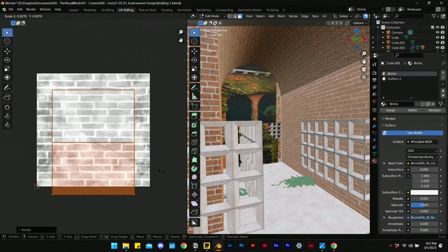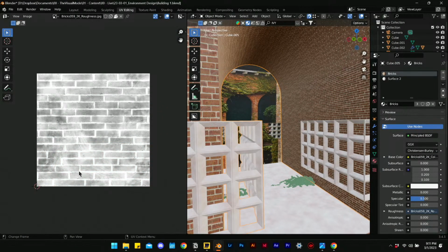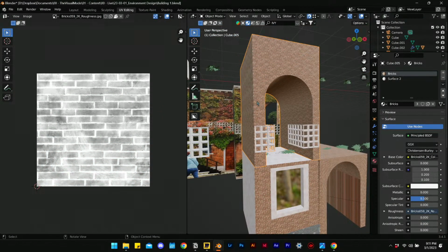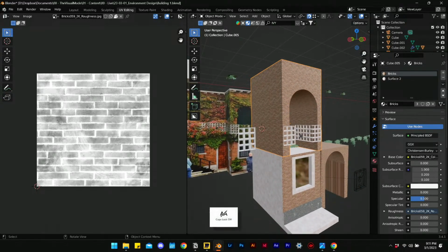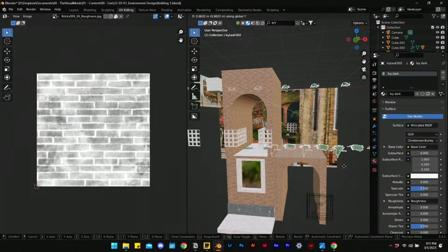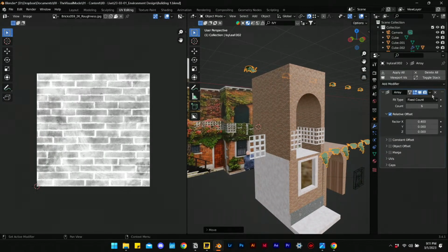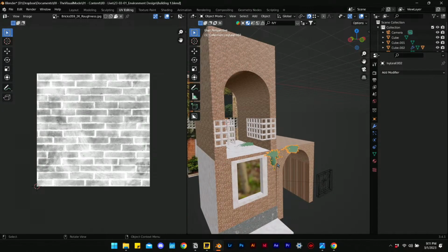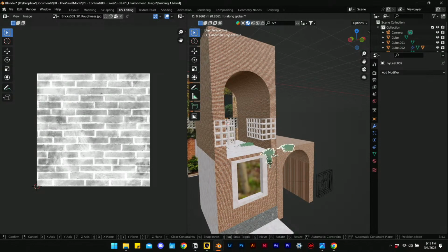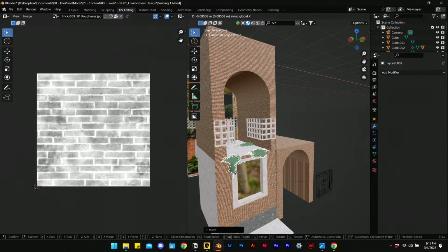This is real building basics, basic building blocks for this environment. I can start throwing IVs over the top of it as well. If I take away the modifiers, the array that I set up on this IV, and I just bring this over. Let's turn off my object snapping.